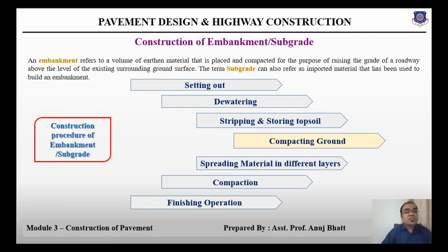The foundation treatment specified for embankments shall be carried out as per the approved drawing. Unsuitable material occurring in embankment foundation shall be removed as per the direction and approval of the engineer, and replaced by approved material laid in layers and suitably compacted to the required and specified degree of compaction.